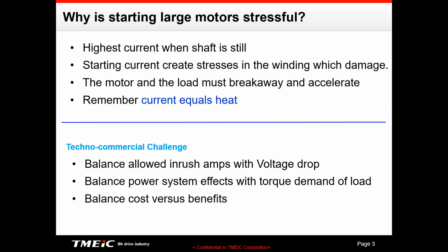Whenever you start the motor from zero speed, it creates a lot of current. During a short circuit event, you have an almost unlimited flow of current, and the voltage, which is the pressure on the utility bus, starts to go down. So remember that you have a high current at standstill.